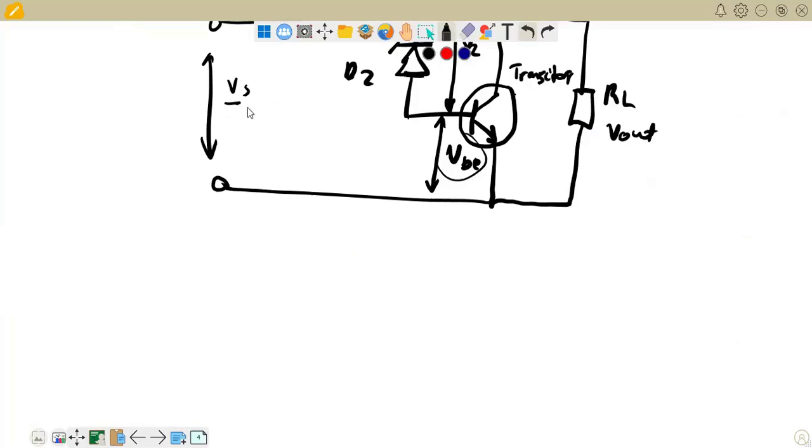If the supply voltage increases, the Zener voltage, which is this one, will remain constant, but the bias VBE will increase. This causes the transistor to be driven to greater saturation in order to let the collector voltage drop. That drop compensates for the increase in supply voltage, and in this way the output voltage is stabilized, which means our V out can be stabilized. That's how regulation has to be maintained. Remember, regulation is voltage stability. So that's the operation of this circuit diagram.